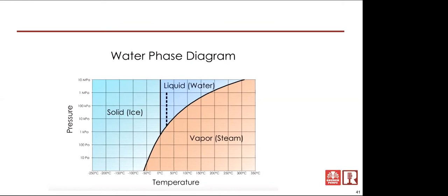But you can see how much a drop in pressure can affect where that water boils or goes to vapor. At 50 degrees C, which is off the top of my head, I want to say it's about 120 degrees Fahrenheit, we've already gone to boiling at 10 kilopascals, or about 1/10 of atmospheric pressure.